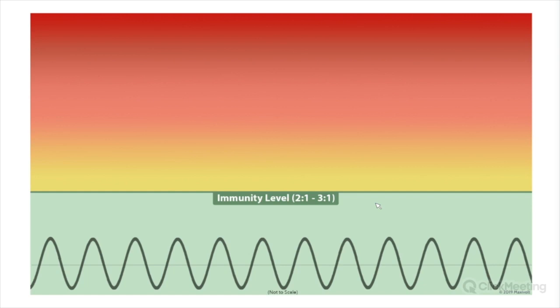So from 240 volts to 360 volts, that's the immunity level of the equipment. If you go above that, it starts getting in yellow and then orange, pink, and then actually red. And if you get way up there, that's going to be the really damaging effects.